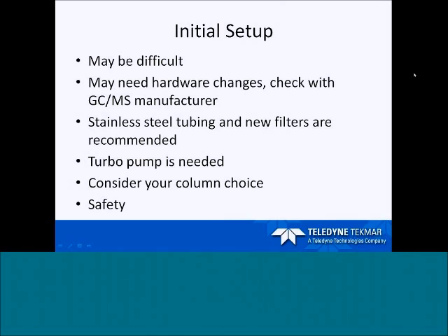So when you're initially setting up with hydrogen, this can take some time and it can be a little bit difficult. So we do want to stress that to you. You may need some new hardware changes, but each GC manufacturer has different stipulations for that. So you may want to check with your GC manufacturer on what needs to be changed.